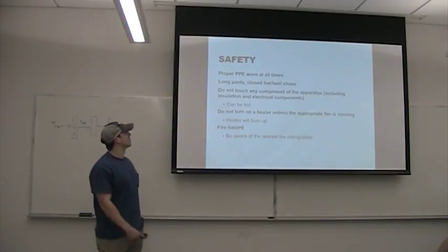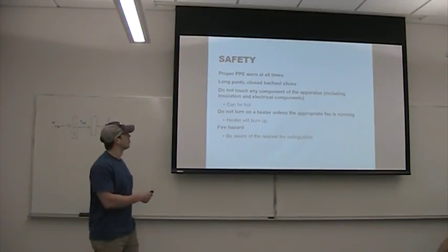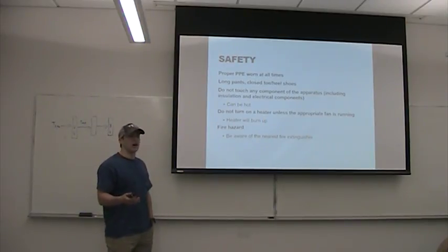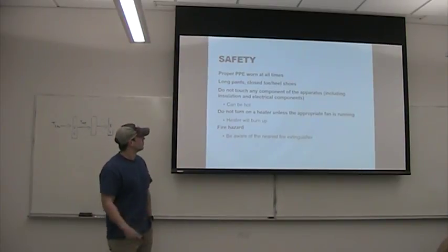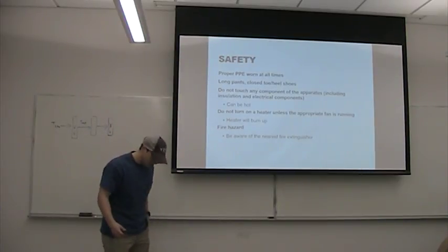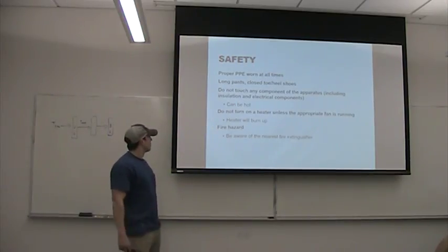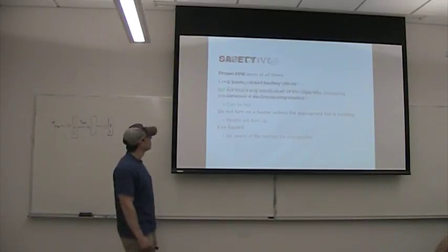Obviously you want your proper equipment worn at all times: long pants, proper shoes. Important right here, do not touch any of the components, as they can get pretty hot. Don't turn on the heater unless the fan is running, or you might burn up the heater. Also, there's a fire hazard, so make sure you know where the fire extinguisher is.